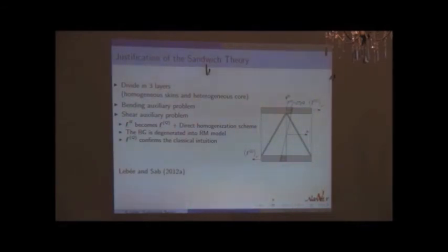And the loading you must apply to the RVE is very intuitive. You take your RVE of the sandwich panel and load the skins with horizontal loads, which put the core into shear. So it's very intuitive and corresponds to what is used in sandwich theory for deriving empirical plate models. It confirms the classical intuition that shear forces put the core into shear through the skins. You load the skins and you put the core into shear.